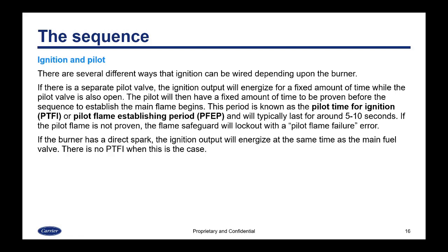and will typically last for around 5 to 10 seconds, and this is one of the timings that you can set with most flame safeguards, or that you choose. If the pilot flame is not proven, the flame safeguard will lock out with a pilot flame failure error. If the burner has a direct spark, the ignition output will energize at the same time as the main fuel valve, in which case there is no PTFI.